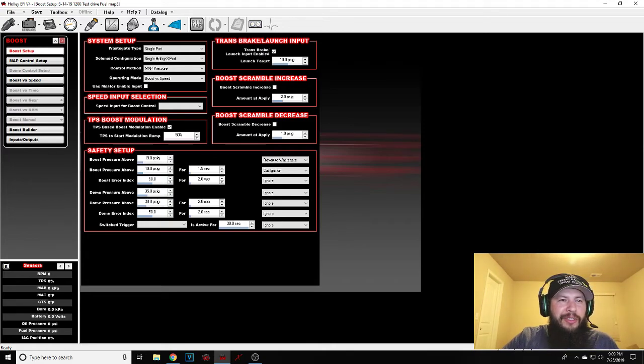Are there provisions for an ABS sensor on the front of the truck? No, not on my truck. So the way we're going to do that is I'm going to try to pick the signal up off the back of the wheel studs, basically. But the way that they're shaped, I don't think it's actually going to work out all that great. So what I might end up doing is basically gluing a magnet to each of those bolts and using that as a pickup. So it'll be a different sensor.